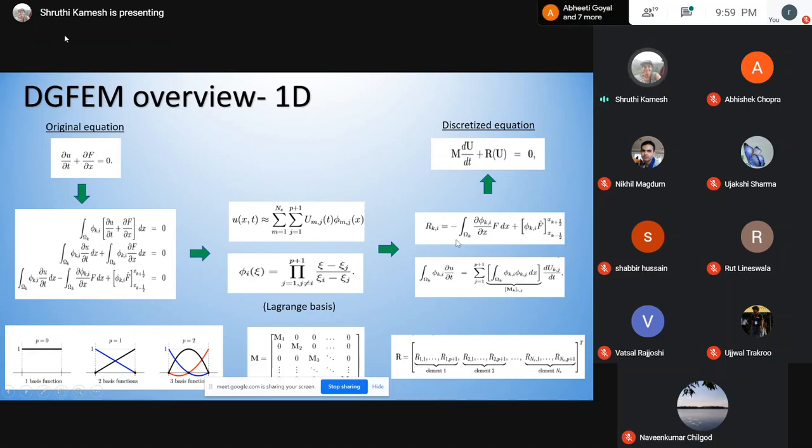You have basis functions and basis gradients, which capture the changes across the element. While modeling a solution across an element, you have some weightage given to the values as well as to how it changes across the element. That accounts for the order as well. As you increase the order, you would expect a finer resolution for the gradients, with more details coming in.